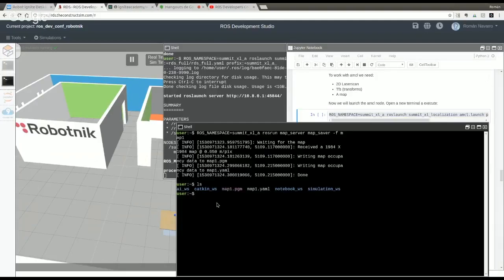We are going to run AMCL. You have here the command to run it. In this case, we are going to specify to AMCL that this is a holonomic platform, so it can move in any direction and orientation, because it is important for the algorithm to compute the localization.